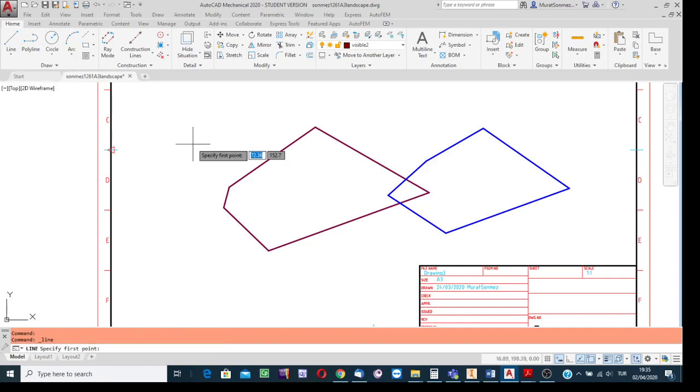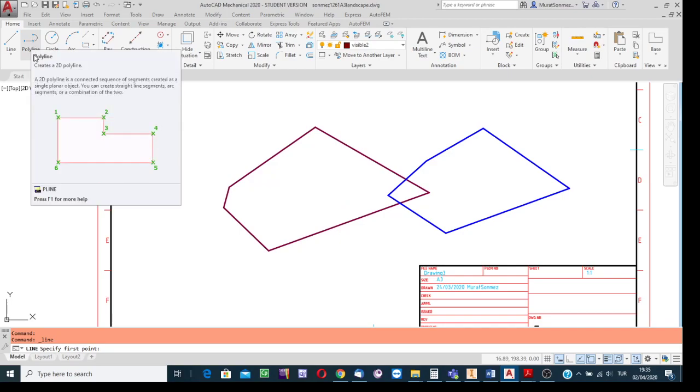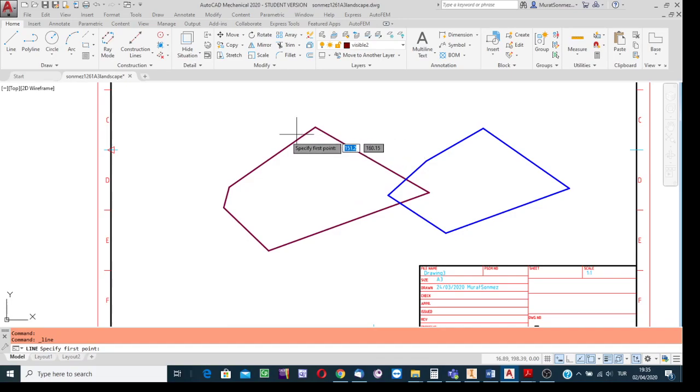I started the line creation process. If you're going to need a region in the end, then for saving time, click on the polyline button. If you're going to have the figure only and not apply a solid model process, then it doesn't matter which one you click.